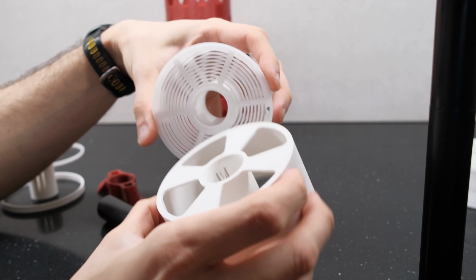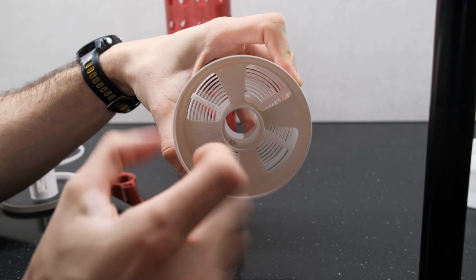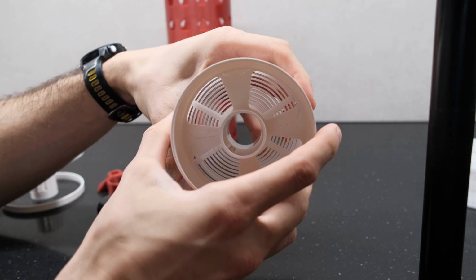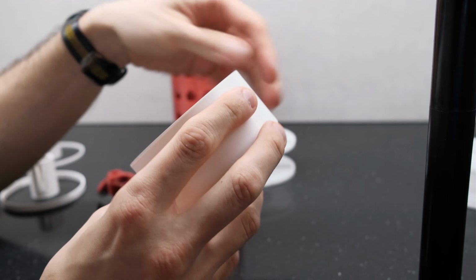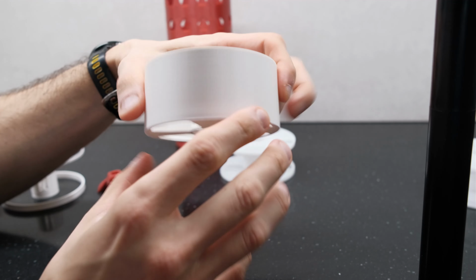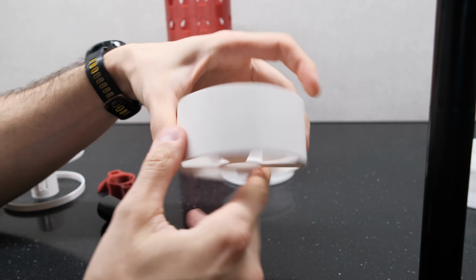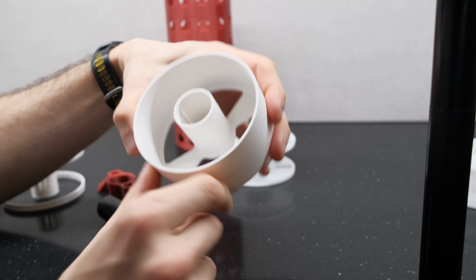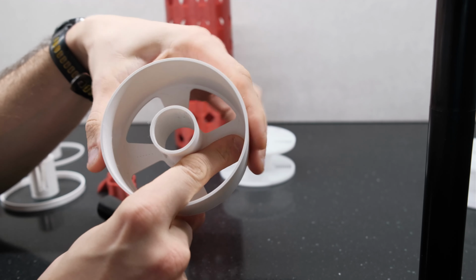But you can see that I tried to do exactly the same as I have here on the reel, so to be more or less transparent, but also have a support for the middle stem. So what I did, I added additional bevels, because I don't want it printed with several layers here and have a 90 degree angle to the walls. So as you can see here inside, I have additional bevels.